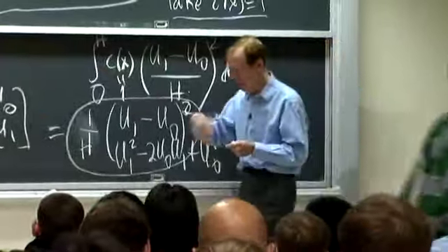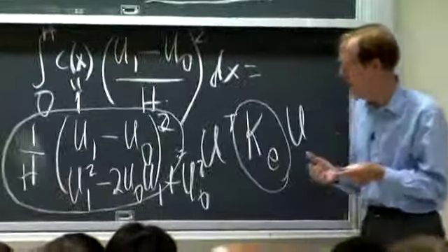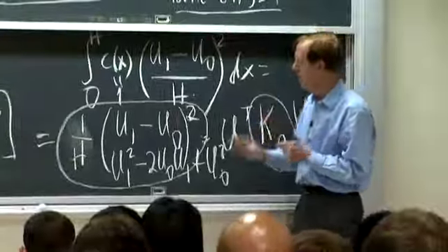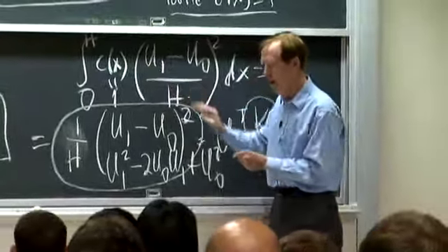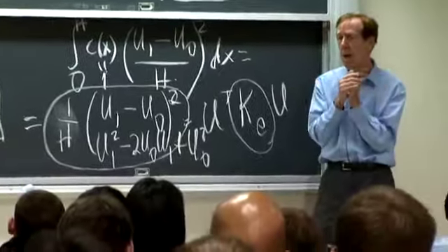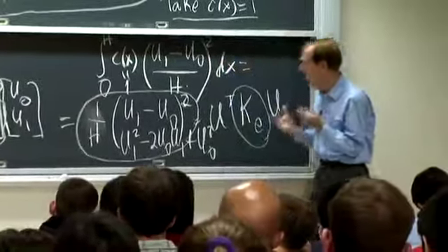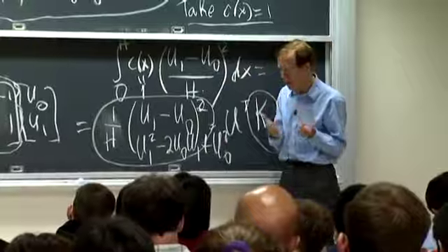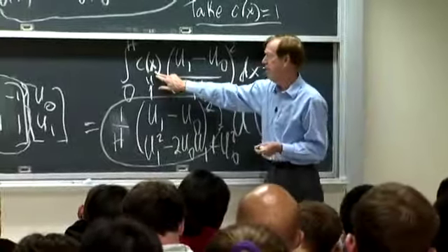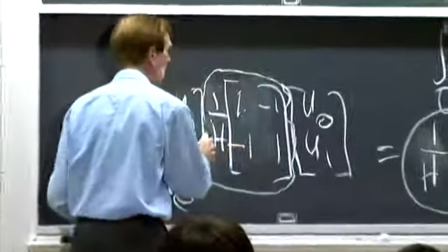So there's a numerical integration here in the creation of these element matrices. And numerical integration is just taking a suitable combination of the values at a few points. Do you know Simpson's rule? That's a pretty high level rule. My suggestion there was just a midpoint rule. Just take c of x at the middle of the interval. Then it would factor out. So I should really put a c here.